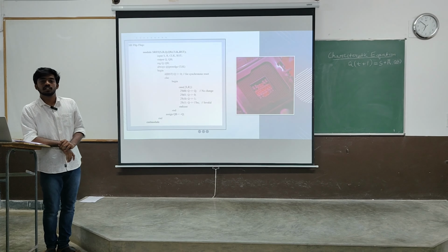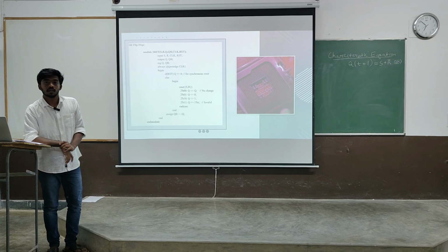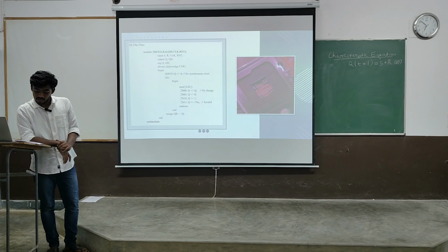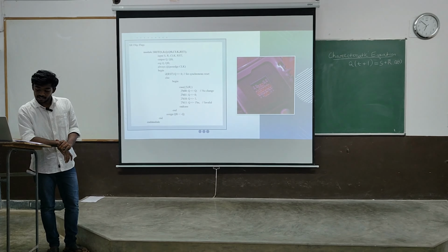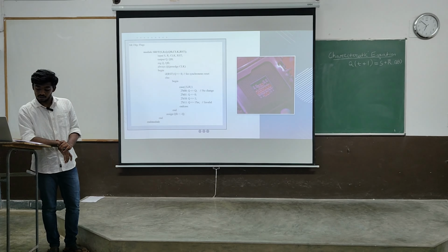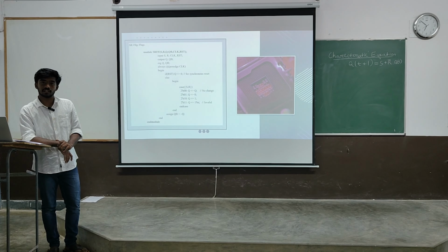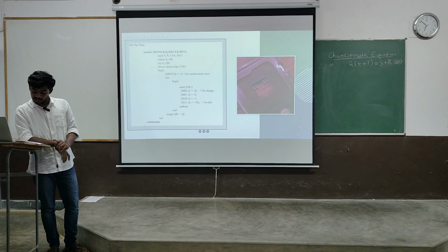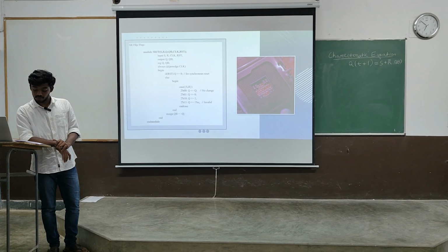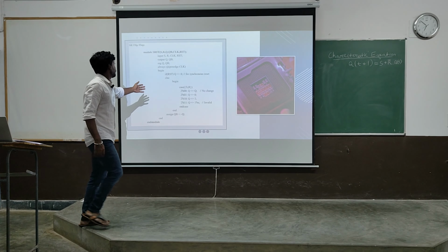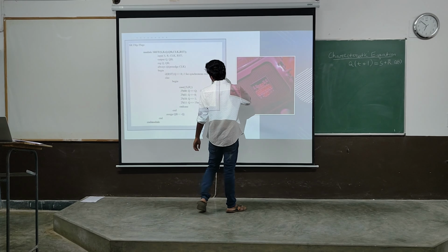Okay guys, so now let us discuss SR flip-flop. SR flip-flop is also known as set reset flip-flop. Here S and R are input control states of the flip-flop. It is a basic flip-flop which stores a single bit, a single data vector. It results in invalid output when both inputs are 1. And this is the Verilog code of SR flip-flop.